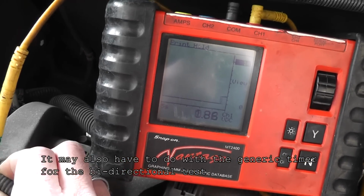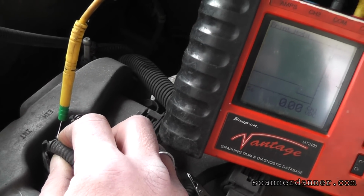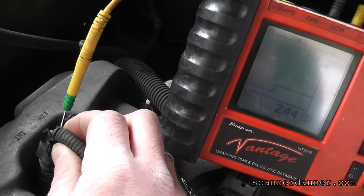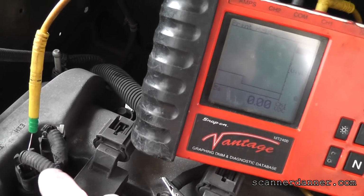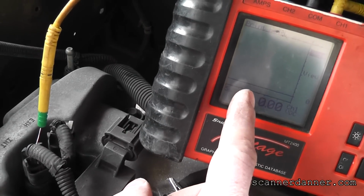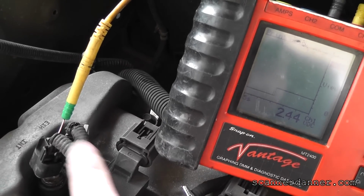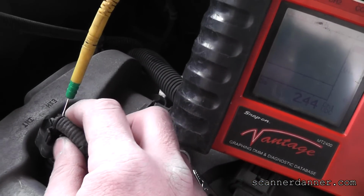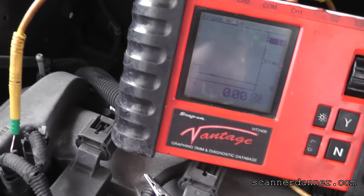But that right there, guys, that's unplugged. And keep your eye on both. That's plugged in. That is a bias voltage that's used in this circuit. And if you know about it, think about this. Why would you do opens and short circuit testing on a harness with 0 volts, say, all the time, when all you have to do is come under here and unplug it and look for a bias? If that bias is there, how's the computer, how's the wiring all the way down? It's good. I mean, that's the idea with this. Get used to it. Start looking for it. It is a huge advantage.